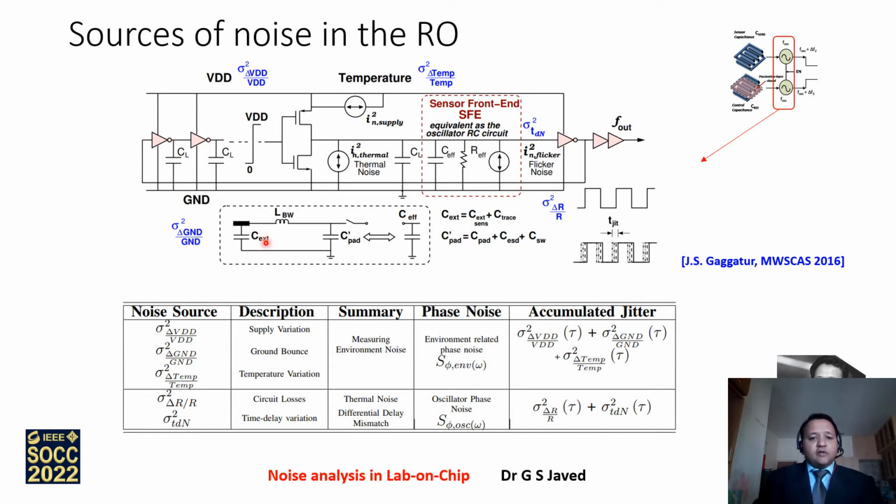If you also look, there is a switch based connection where the C pad of the system, the bond wire capacitance of the packaging, and the external stray capacitance Cx are also modeled, giving a C effective here. In this case, the Cx comprises the externally used sensor capacitance and the board trace capacitance that is brought out.